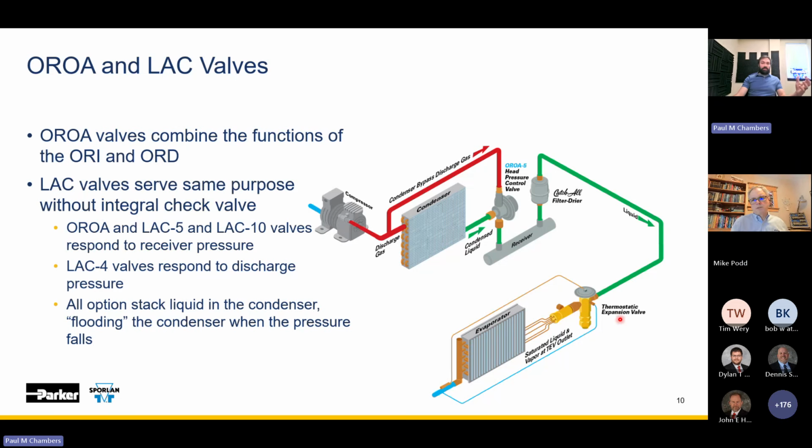So to your point, you said we need that pressure. We need liquid as well, because that's what's going to boil off in the evaporator. But if we can't get pressure drop, even if you have liquid, you're not going to get that desire for expansion and boiling that you would see, right? We need inlet pressure high enough so we can see a satisfactory drop through the expansion device and evaporation in the evaporator, to get that volume. Yeah. Okay.